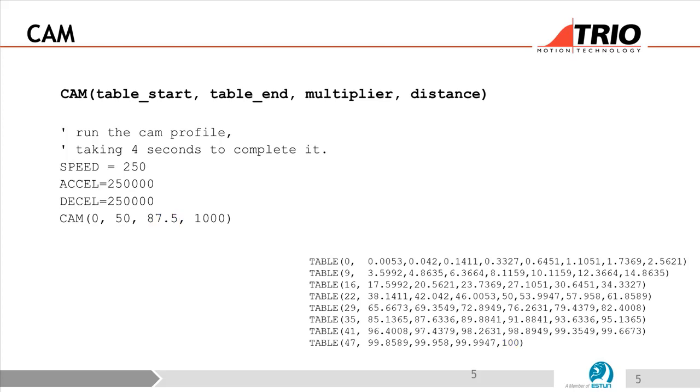There's a way around this kind of arbitrary way of scaling it, in that if you know your units as a certain value, so in this case you've been using units of 50 in our little examples. If you make your cam profile in the table start at 0 and end at 50, that whole table represents 1 millimeter. So then your multiplier there would be in millimeters. So you can actually make it more human usable in that way, simply by making the cam represent whatever it is you've got, whether it's 1 millimeter, 1 revolution, 1 inch, 1 foot.